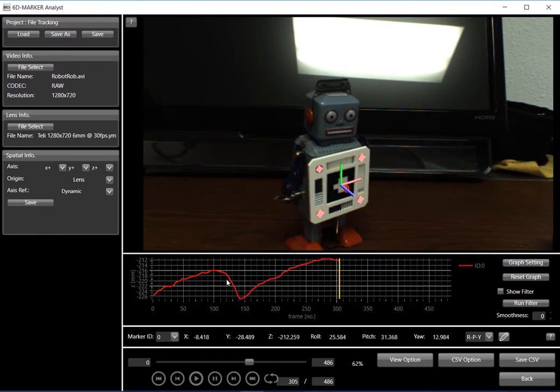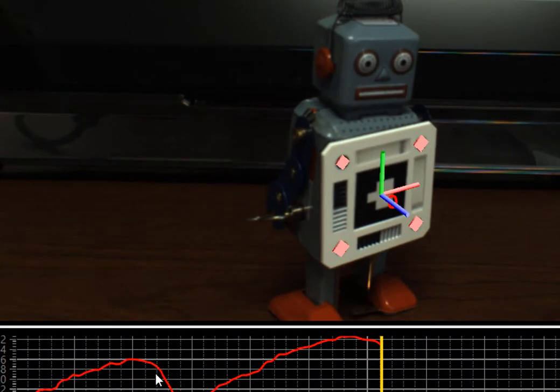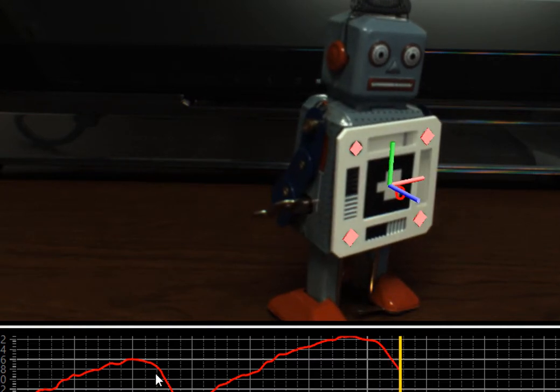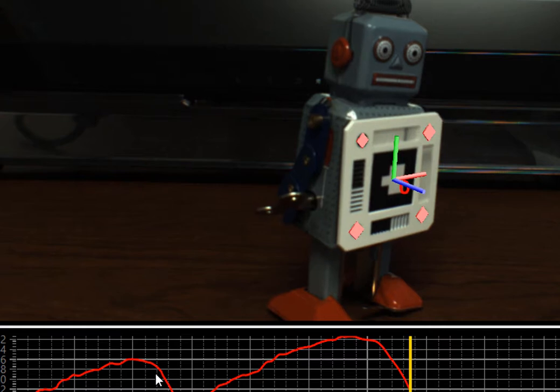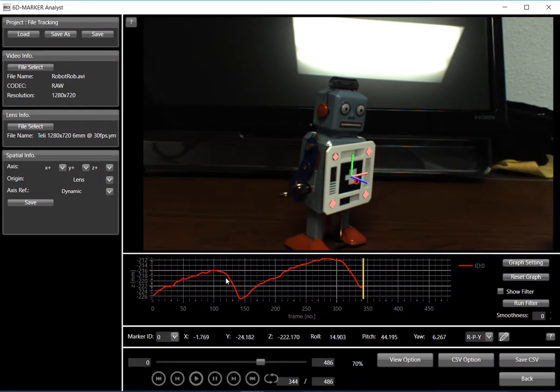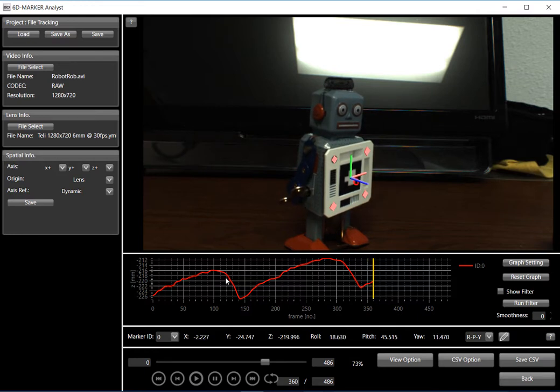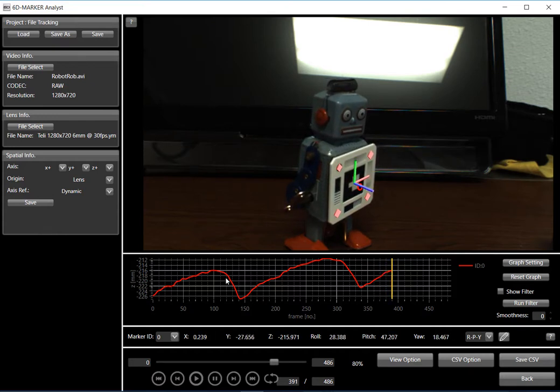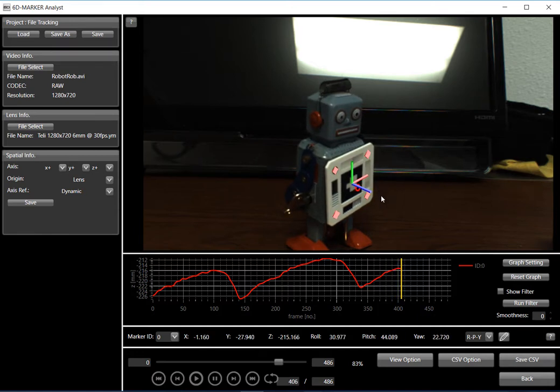It's important with all these recordings to make sure the entire marker is not obscured. We need to be able to see all four corners as well as the lenticular components of the marker. You'll notice when you use this that the marker can almost be oblique to the camera view and still maintain a good track, but illumination levels and having the entire marker and a minimum of 40 pixels covering between the outer dots on the marker is critical to maintain a good solid track.